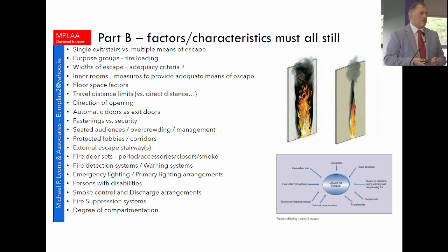Same issues to do with working out your occupation figures. It's all space factors on the numbers of people per square metre. All the typical fire safety measures that we take, whether it's detection, emergency lighting, fire-rated screens, fire-rated doors, all of those things still have to be included in a building that is a performance-based design, but there's no rules telling you where exactly you must do it, other than what are the consequences when a fire occurs in each of the cells of the building that you've designed for.